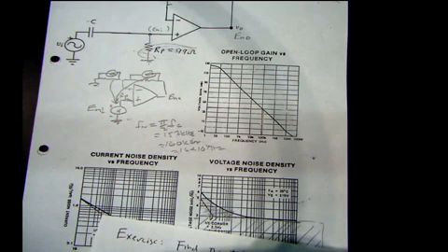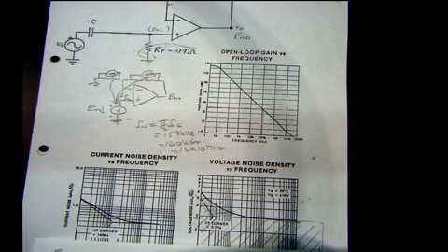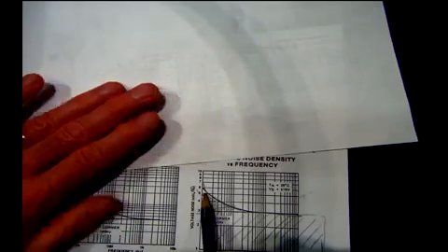When we're calculating the area of the voltage noise, we change the unit to multiply by square root hertz. But the noise is changing with frequency. Yeah, that's why I've multiplied by that. How about we just look at it as the white noise component here, that bit underneath here? We just forget about that change because that's happening at very low frequencies.